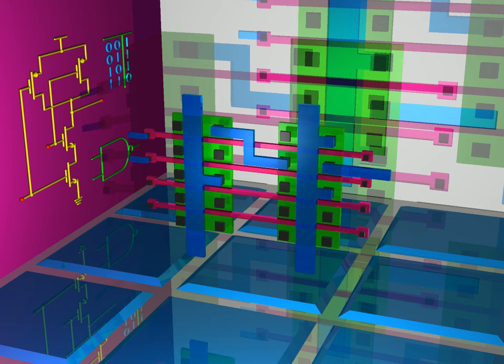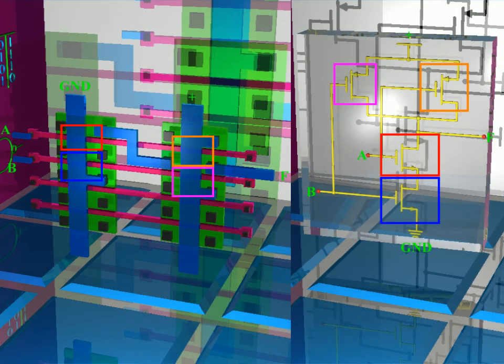In case it is still a little unclear, here's the schematic and the mask layout compared. The two side-by-side images show how the schematic matches the IC mask layout. For this discussion, G and D is ground, plus is VDD, F is the NAND gate output, A and B are the NAND gate inputs, and the colored rectangles surround the individual transistors, which are color-coded to match.